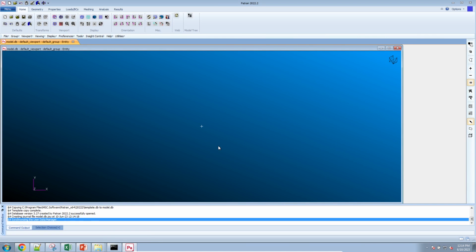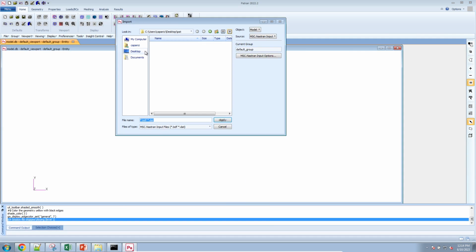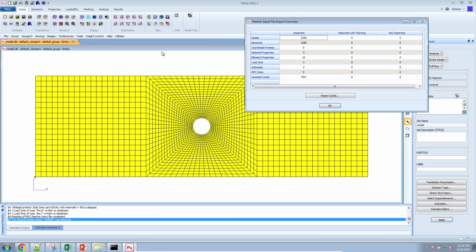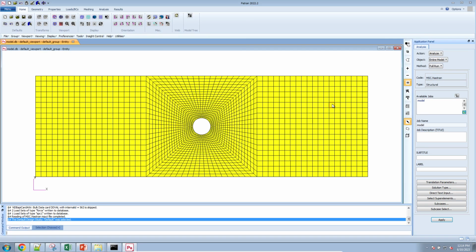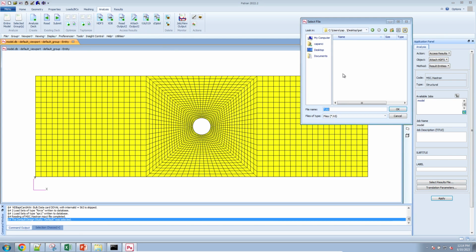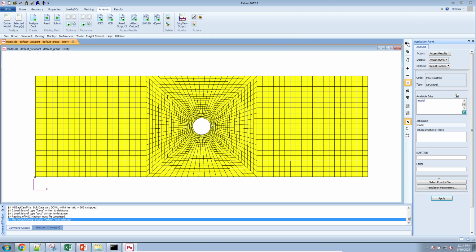So let's go ahead and confirm that value. And while I'm doing this, let me explain that again. If it's a compression or a tension load, regardless of the stacking sequence, you'll most likely get the same failure index. But if you have a load that causes bending, the stacking sequence will influence the failure indices. That's why you saw for the first subcase, which is a purely tension load, that before and after the stacking sequence optimization, we got the same failure index.